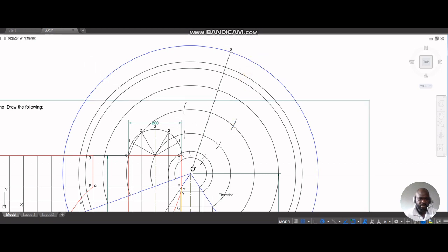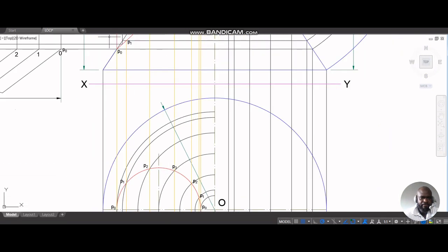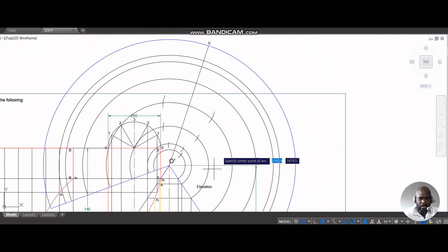Okay, the next point is P2 to the base. I'll look at P2 here and extend my compass here. I get 30.9, take that as 31. Please note that what we're using is approximate values, right? Sit on P2 and with that radius, same radius, not moving your compass, create an arc here with the same radius. Duplicate the same arc on the other side of the cone.